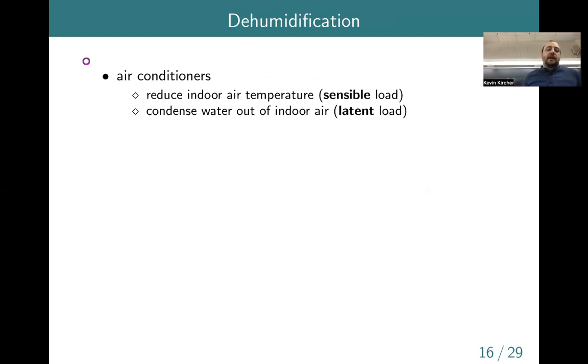Okay, so one thing that air conditioners do that heat pumps don't is control humidity. That's actually why we call an air conditioner not just a cooler. We call it an air conditioner because it also conditions the air, meaning it removes moisture from the air. So the way that typically happens is your heat exchange coil has very cold refrigerant running through it. When warm, humid air runs over something cold, just like a glass on a hot summer day, you get condensation on the outside. And so that coil basically absorbs moisture from the humid air, and then that typically pours off into some pan and is piped outside or down a drain.